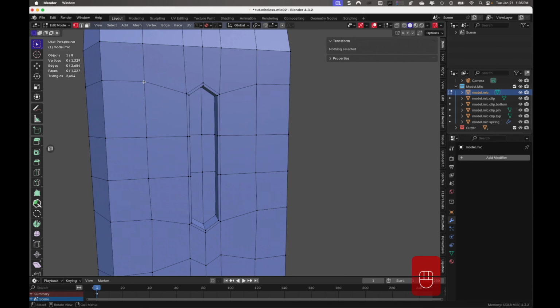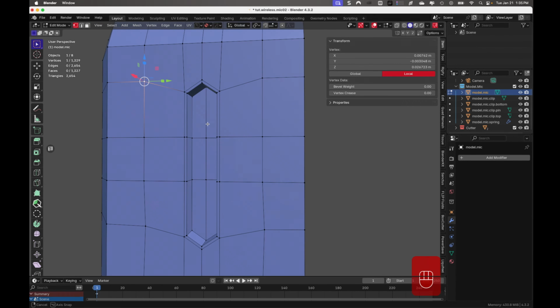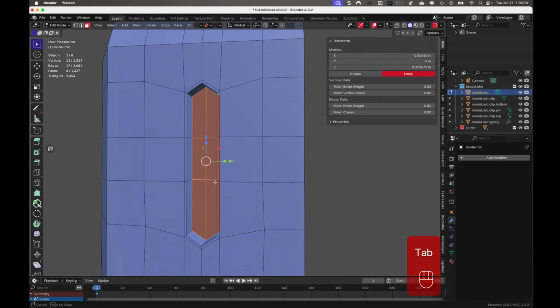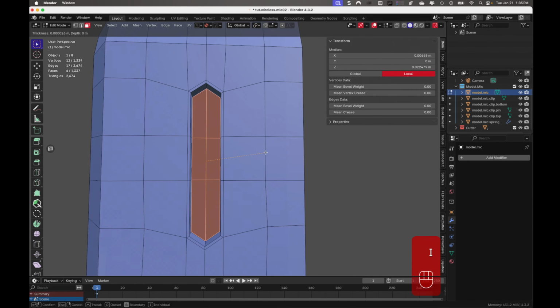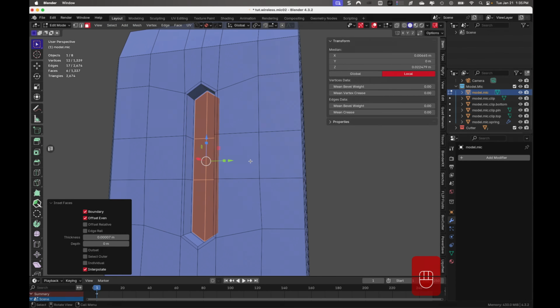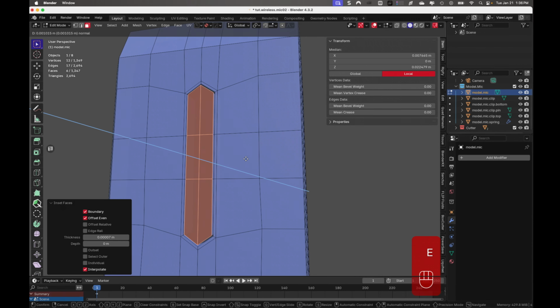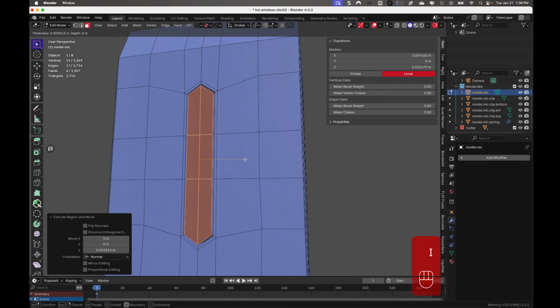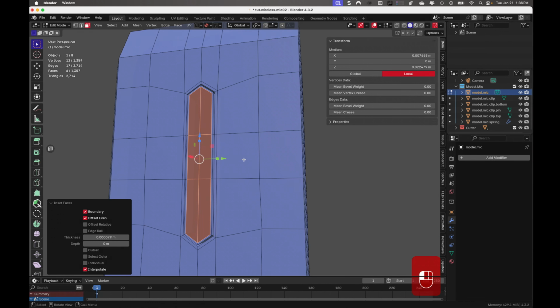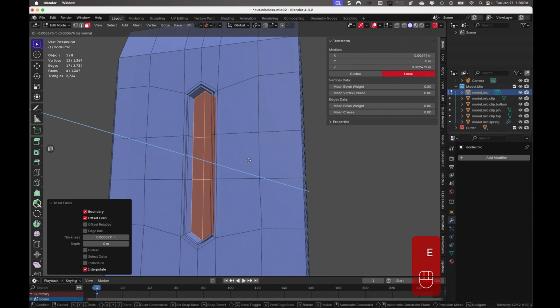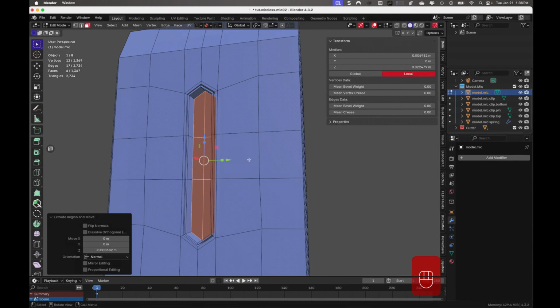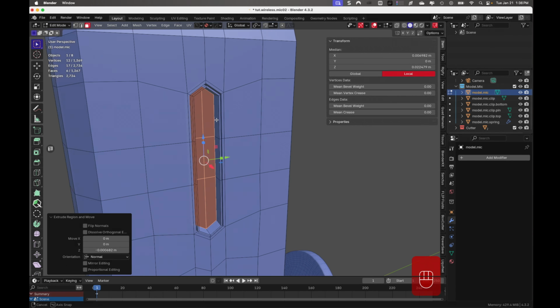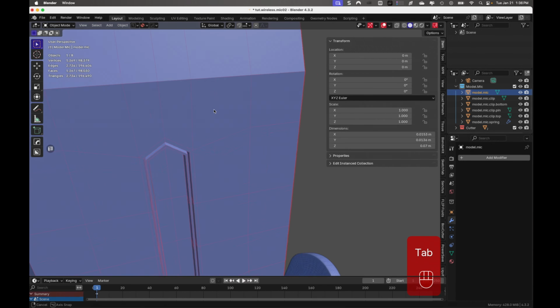We're good. All right, so let's start focusing on modeling in some detail to this port. Like I said, I want one ring to be that aluminum ring that you see on that port. So I'm going to do an inset when I select that bottom portion there. I'm going to extrude it out, inset it again, and extrude it back in. That creates that outer ring of that metal. Okay, and I'm just going to bring that back in as deep as it needs to go. So just that quick, we created that outer ring.